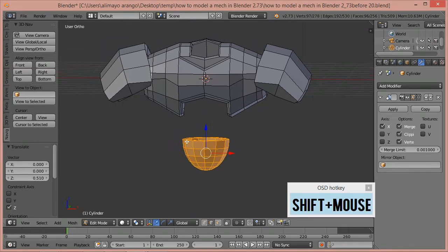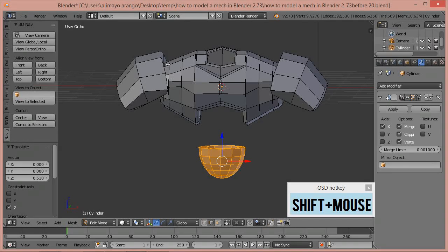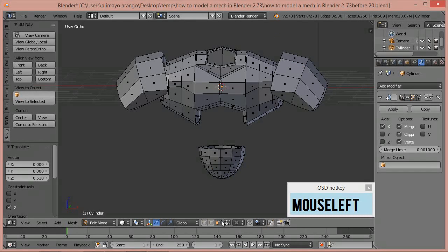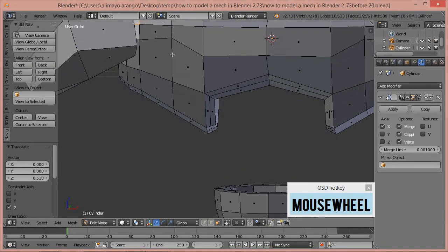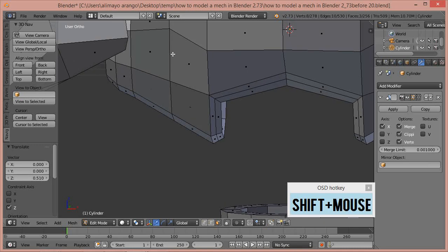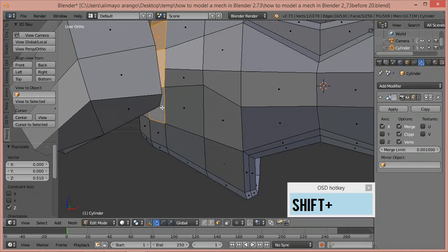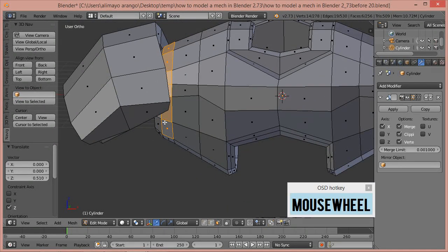Remember what I told you about duplication. So what we're actually going to do now is we're going to go to Face Select, select here, hold Shift, and select all of these faces. Let me zoom in. I let go of Shift to zoom in. Now I'm holding Shift and the middle mouse button to pan. Just selecting here again. So I have these faces here, right?